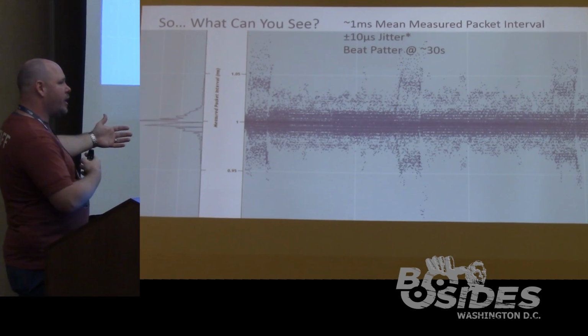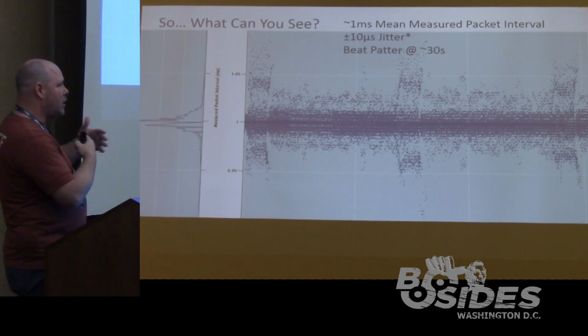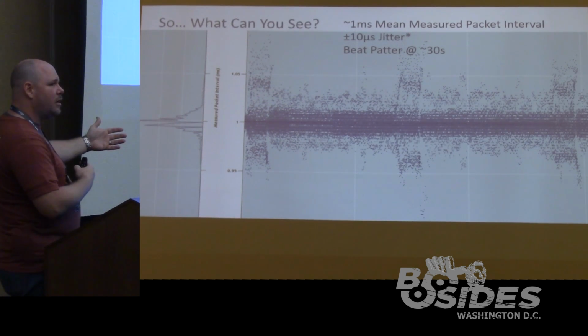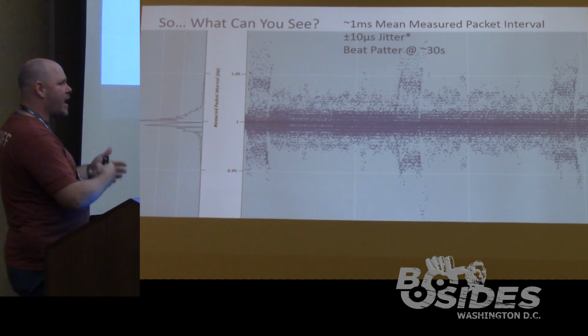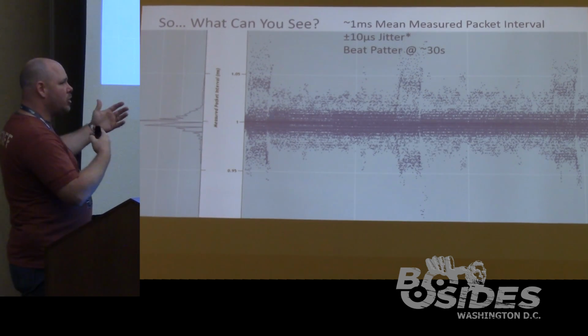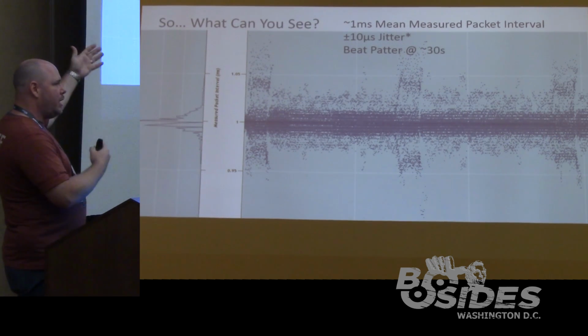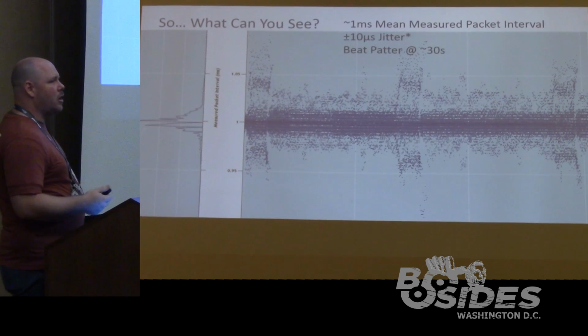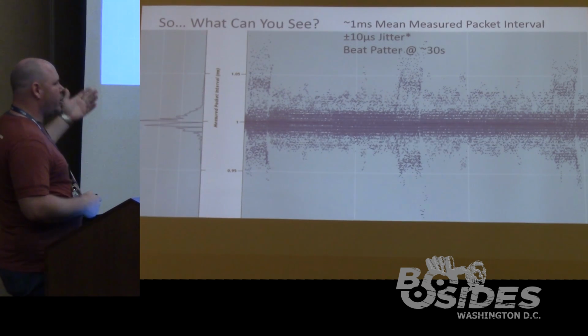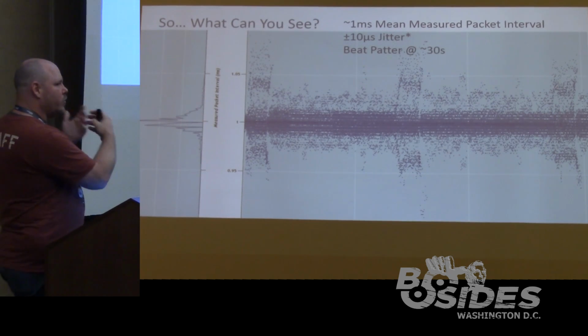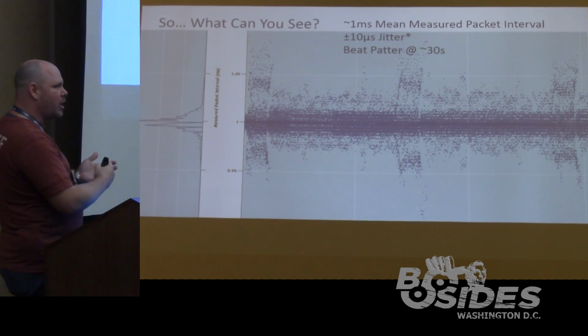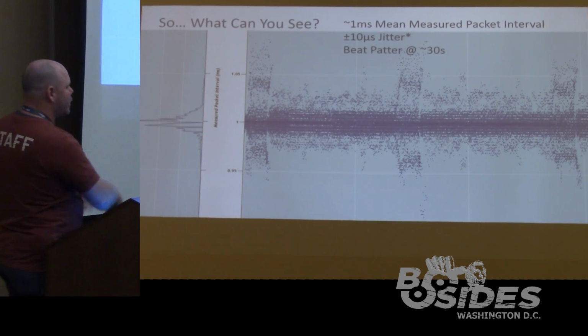If you've done the signature analysis, or at least signature collection earlier in your process, factory acceptance testing, SAT, commissioning, things like that, you would know that this device looks like this, and if I see this down the road, it's nothing special. So this is where you get into, okay, what does it really look like? Not what it should look like, but what it actually looks like.